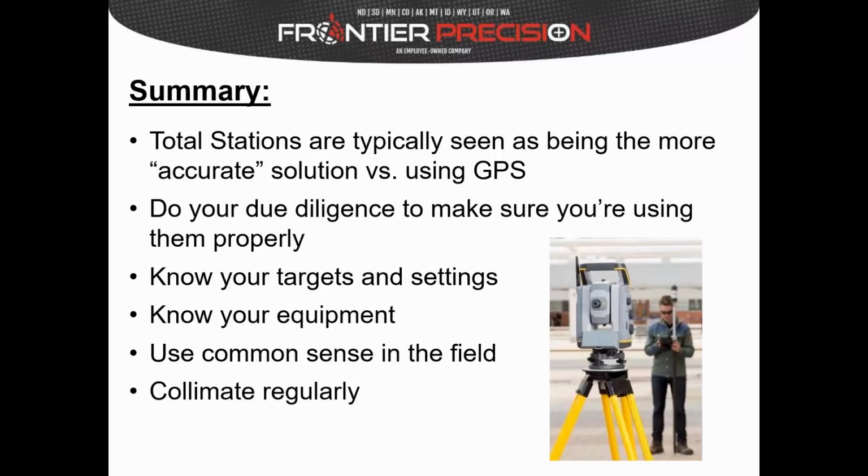Collimate your instruments regularly. It's important, those three that I went through, it's important to do those checks routinely, especially on big staking jobs or things where you're setting control or you need to be accurate. It's important to do those checks, and if they're not quite what you feel comfortable with, run through the collimation and try to tighten them up a little bit.